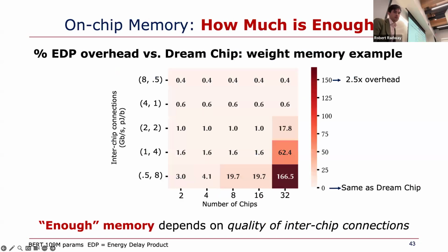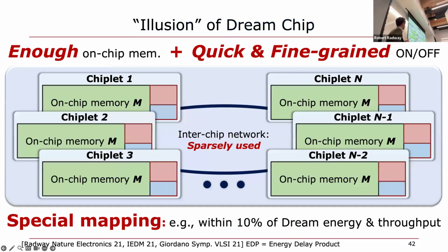So we have to look at how we think about multi-chiplet systems. A lot of my work on multi-chiplet systems has basically been taking these ideas of very fine-grained power management and applying them not only on the chiplet, but inter-chiplet as well. This changes how you would map and schedule your workload, because you care much more now about inter-chiplet network energy and the static power for that, versus what's actually happening on the chiplet, because you've minimized the chiplet energy so much. So this is, again, the kind of bottleneck. What is the energy bottleneck? Instead of the idle power of your chiplets, it's how you think about your communication on your network.